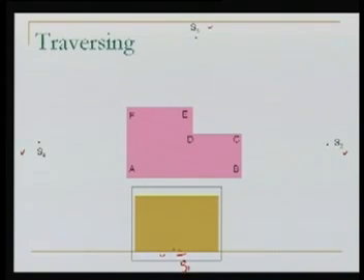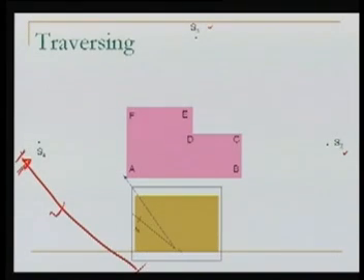Now from this S1, we draw rays. Rays means we use the alidade and start drawing them. First we sight the station S4. We draw this particular line. I measure this distance, because this is the distance between our main stations.